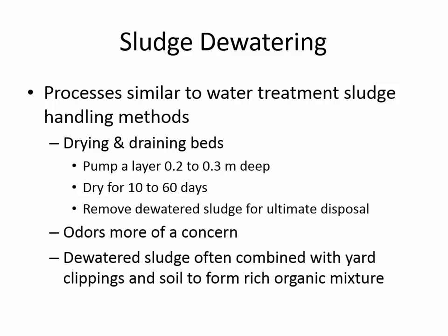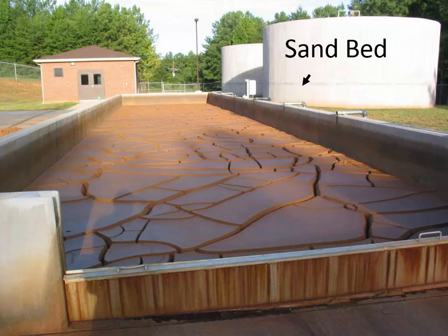What we will see when we go to the University City treatment plant is they're dewatering the sludge by just drying it out. This stuff has a funny name. It's called sludge cake. It's a cake you never want to eat, right? But you're just letting the sun do the work of evaporating the liquid, and what's left behind is a material that could be used for fertilizer and have the nutrients recovered. It's just dried out over a sand bed.